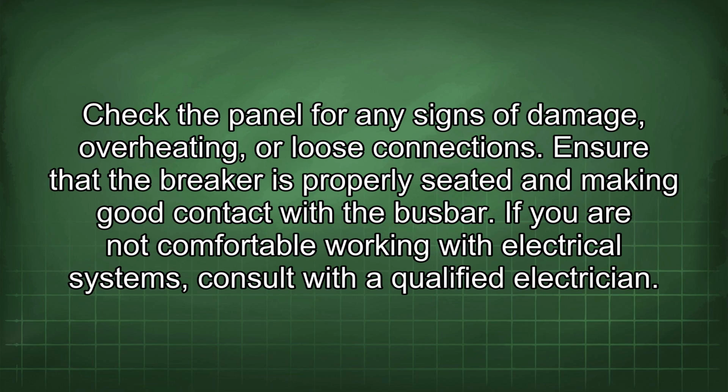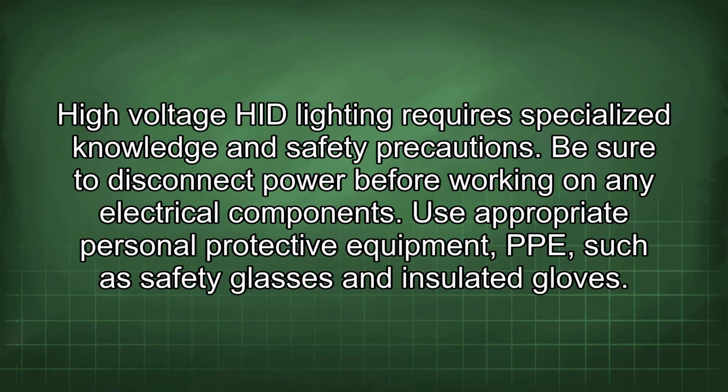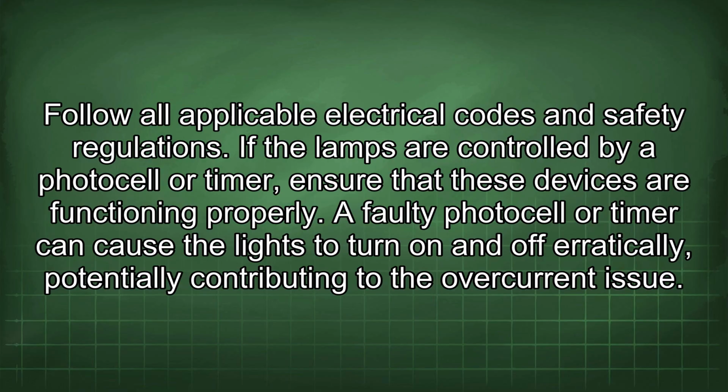If you are not comfortable working with electrical systems, consult with a qualified electrician. High voltage HID lighting requires specialized knowledge and safety precautions. Be sure to disconnect power before working on any electrical components. Use appropriate personal protective equipment (PPE), such as safety glasses and insulated gloves. Follow all applicable electrical codes and safety regulations.